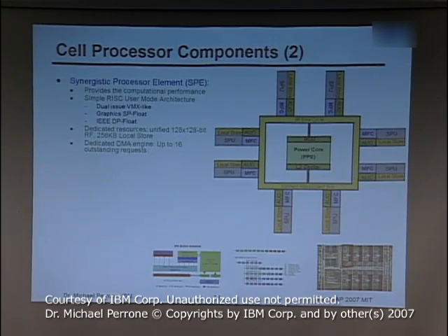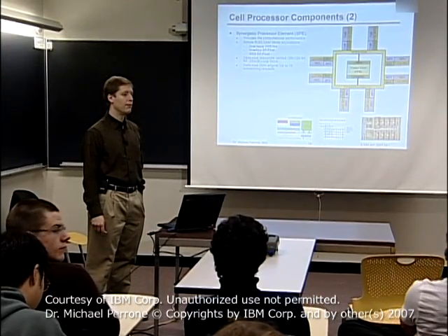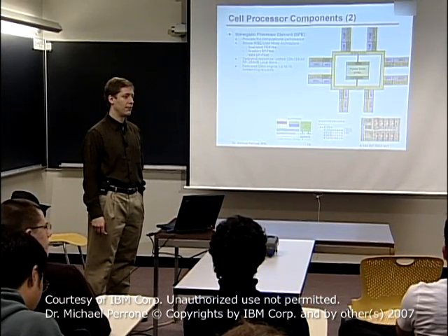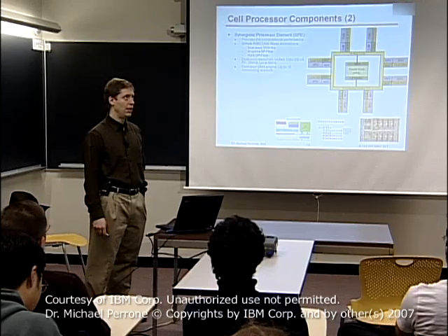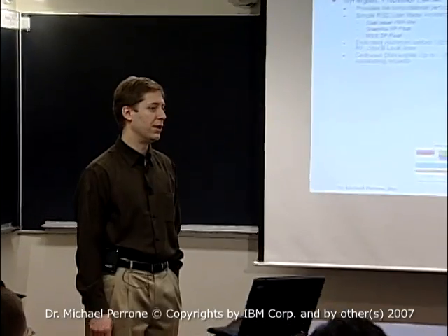Okay, can I ask a quick question? Yes. Just like you said, you could compile anything on the power processor, it'll be slower, but you can. And you also said the cell processor is in and of itself an awesome processor. Can I compile any C code to that as well? C code would compile. There's issues with libraries because the libraries wouldn't be ported to the SPE necessarily. If it had been, then yes.